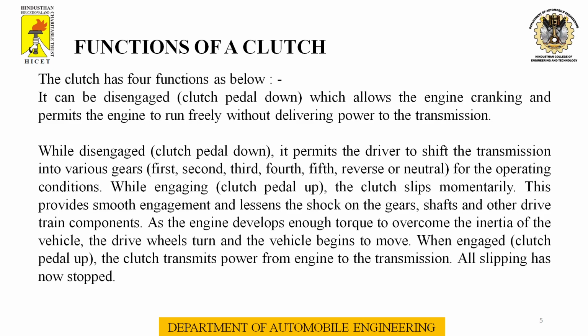Function of the clutch. It can be disengaged, which allows the engine cranking. It permits the engine to run freely without delivering power transmission. While disengaged, it permits the driver to shift the transmission into various gears for the operating condition. While engaging, the clutch slips momentarily. This provides a smooth engagement and lessens the shock on the gears and other drive train components.